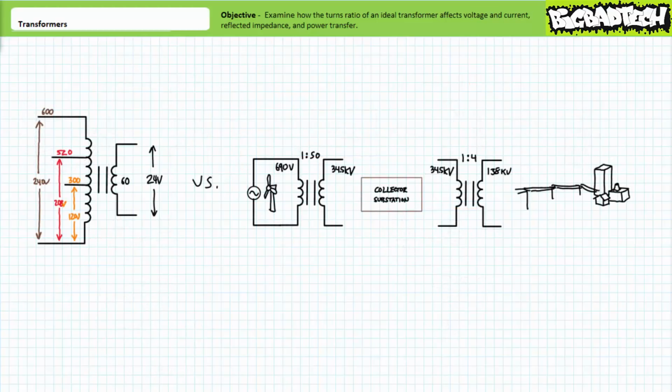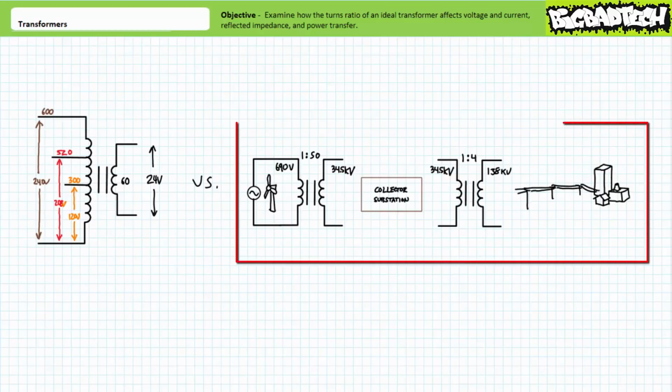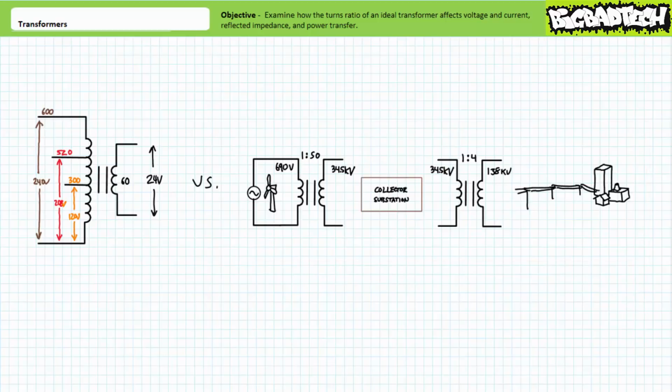Before we move on, compare and contrast not only the step-down versus step-up relationship of these past example transformers, but also their larger roles. In the first scenario, we made use of a transformer to simply power the control electronics of some heating or air conditioning device, whereas the next series of examples dealt with transformers designed to transmit a massive amount of primary power from some distributed generation equipment to a city some distance away. In this sense, the first couple of examples might be referred to as control transformers, meaning a control transformer is designed to power low-power control electronics only, and not massive amounts of primary power.